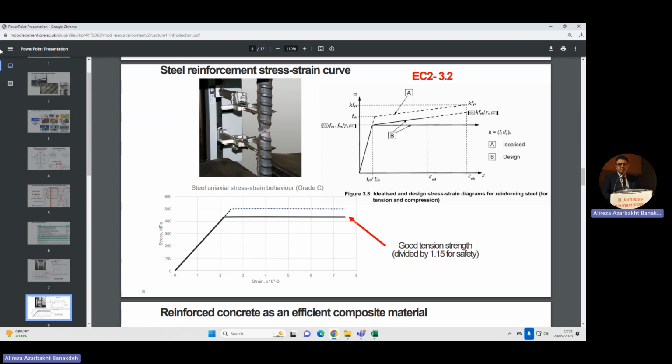And here we were working about 30 megapascal, right? Divided by 1.5 to get 20, right? We were working here, right, for the concrete. Now we're working for 500. It's way far away from that one. That's the difference of concrete and steel.